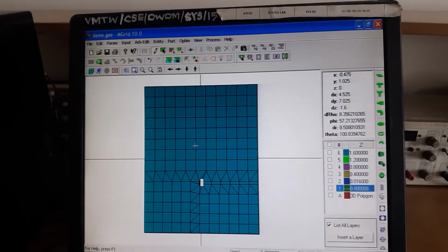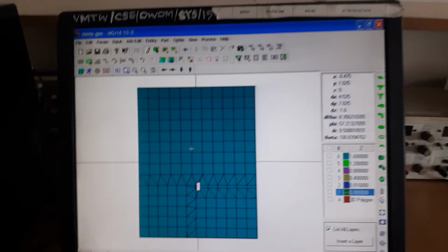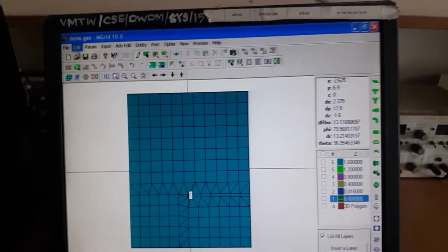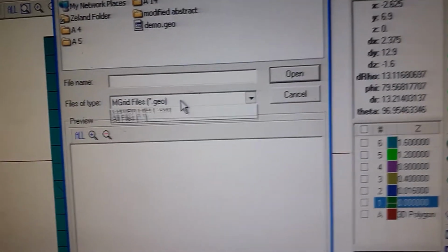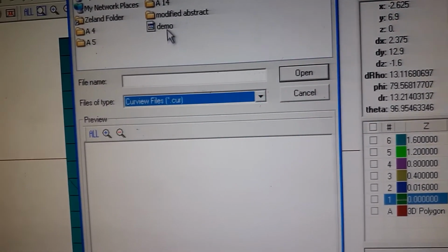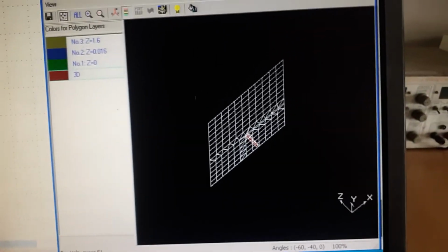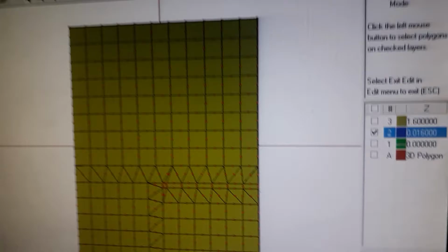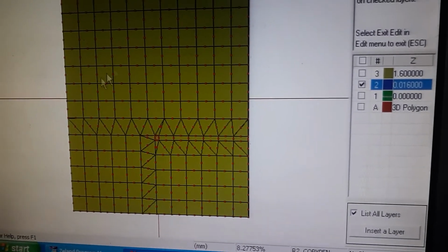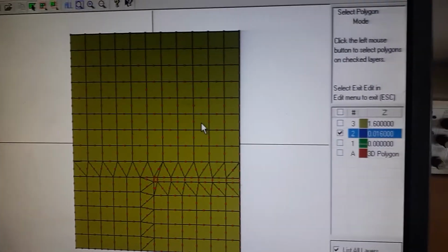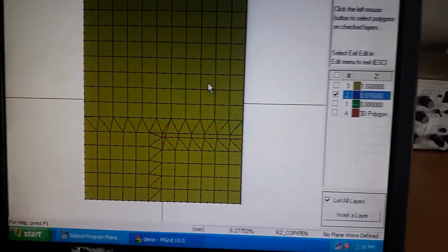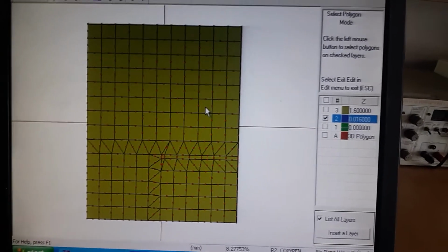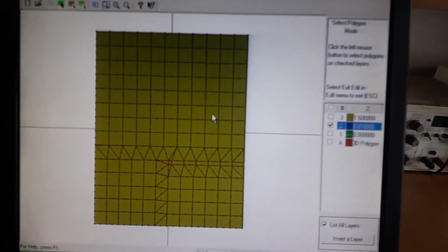through the IE3D software. Now in the IE3D software, there is another thing. If we want to see the current distribution file, we can go to curve view, where demo is there, and that shows your current distribution file. You see there are some arrows. This is your current distribution file. It shows how the current moves towards the patch, across the patch, and how the current is flowing.